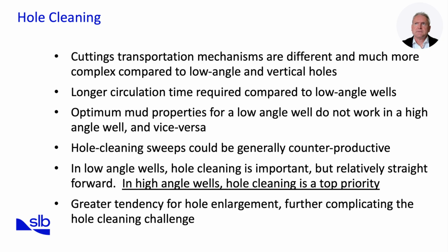Another factor is that mud properties optimized for vertical wells are not effective in high-angle holes. Viscosity, density, and gel strengths must be adjusted to suit the trajectory. Interestingly, hole cleaning sweeps, commonly used in vertical wells, are often counterproductive in ERD. They may not effectively mobilize cuttings beds, which can disturb wellbore stability.